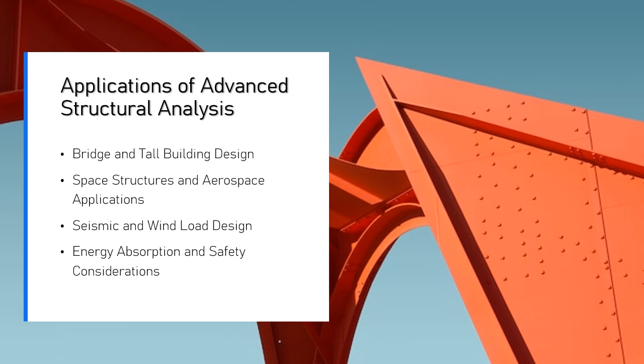3. Performance-based design and optimization for skyscrapers. Case study: Shanghai Tower, China. Challenges: the Shanghai Tower is China's tallest building and needed to accommodate earthquake and wind loads, as well as provide optimal energy efficiency and occupant comfort. Advanced analysis. Performance-based design principles were used in combination with finite element analysis (FEA) and dynamic response analysis to evaluate the building's response to wind forces and earthquake motion.